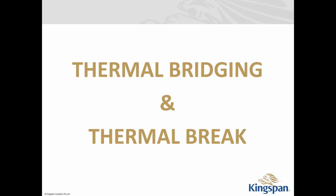They had a timber frame construction with an R2 bulk insulation inside it, FC sheeting on the outside, R2 insulation in between the studs, and a 10 mil plasterboard on the internal. They measured the R value of that, and it was achieving an R1.8. So although you had FC sheeting, R2 insulation, and 10 mil plasterboard, they still measured the R value as an R1.8.